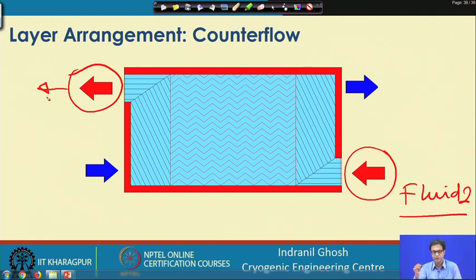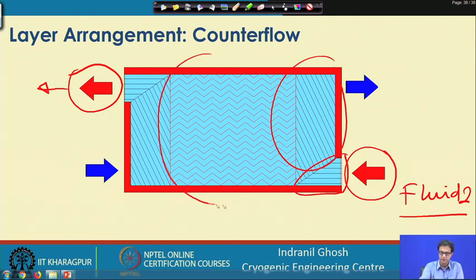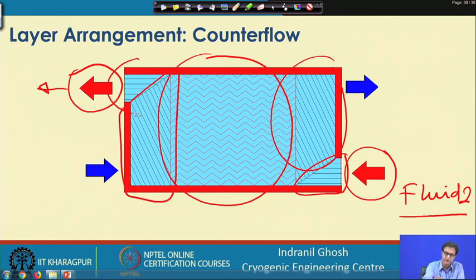So, now here also, as you can see, we have a distributor on this side, then a distributor on this end, and this is the main fin. This main fin is a kind of wavy fin, or you can say a herringbone type of fin. Then we again have a distributor on this side and a distributor on this side to take it out. So, now what we have is basically one layer of the cap sheet, then one layer of fluid